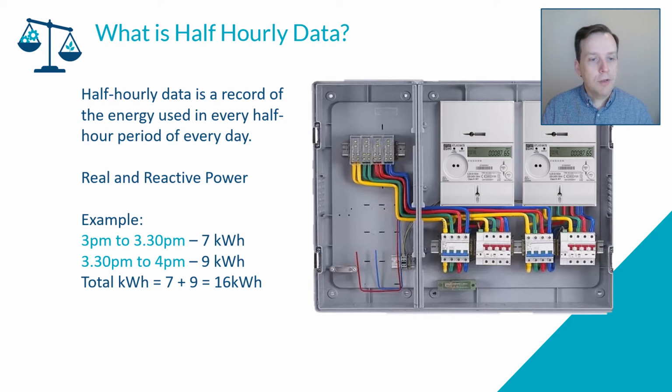The meters record real and reactive power, and I'll give a bit of an explanation for that. Also, some meters will record import and export. So if you're generating on site, you may well be able to use the same meter to record export. So if you have significant solar and you're exporting, and your demand on site is less than the total solar generation midday in the summer, then you'll be in the fortunate position to export to the grid, and you may actually earn cash from that process.